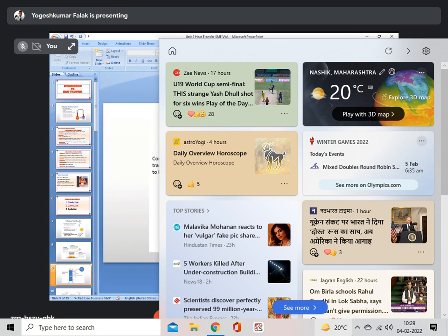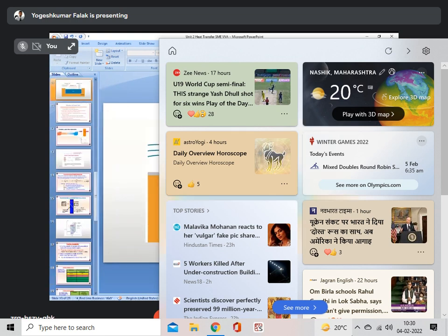So this is one of the heat transfer examples in which you can see conduction and convection, not radiation. Also, there is some evaporation that this pool has. So conduction is taken in this case as 5% only. Convection is taken as 20% and radiation is taken as 10 to 15% in this case in the pool, whereas 65% gets evaporated. So during the evaporation process, some of the heat is convected, radiated, and conducted.